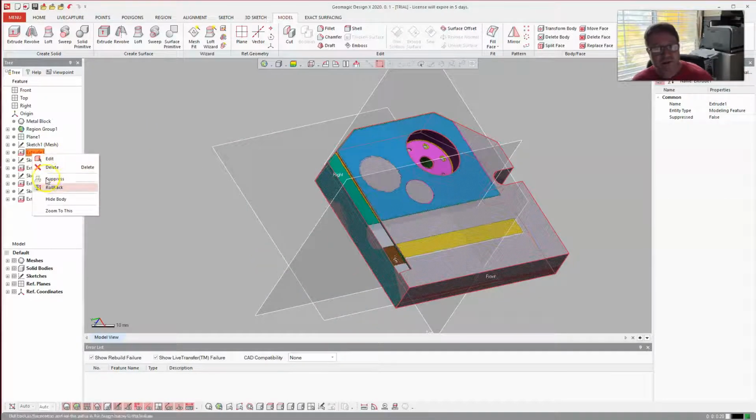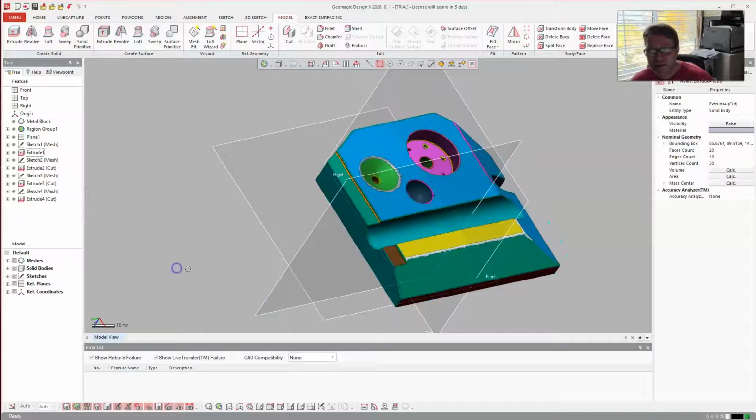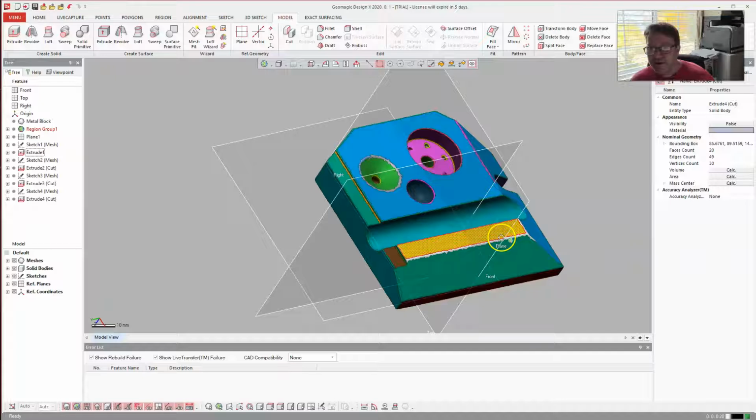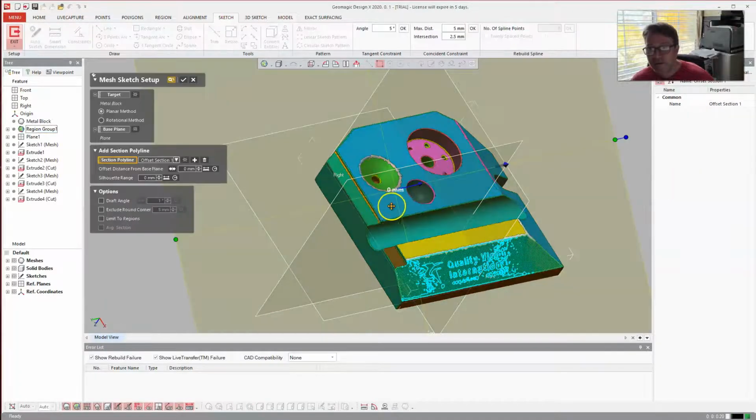And let me hide this again. Extrude, hide body. Once I do this plane, I can do a gigantic rectangle, large, extrude this way. It's going to take care of that awkward looking area, and the same with this side. So let me take care of this plane real quick, just to show you